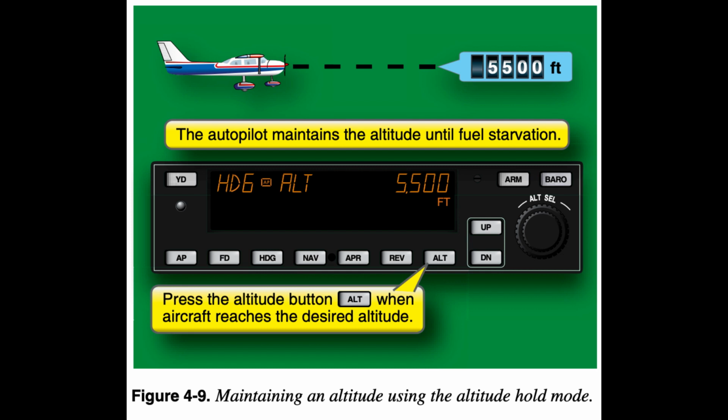An auto-trim system is capable of automatically making any needed adjustments to the pitch trim to maintain the aircraft at the desired altitude and in a properly trimmed condition. Pitch control pressure applied with the altitude hold mode engaged will cause the autopilot to trim against you.